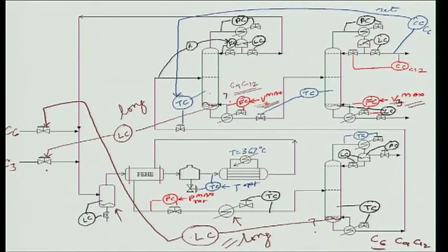We did the simulations, and it did turn out that for the disturbances we considered, which were pretty large, you are able to operate the process with these levels fluctuating in a larger band, but not hitting high level or low level alarm limits. So in this control system, what I have done is essentially transform the variability to the levels.